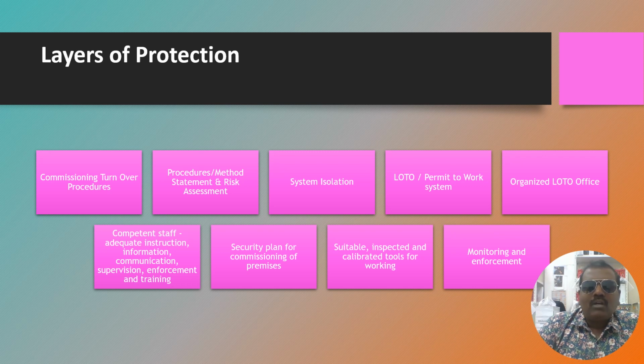How to remove this? A motor is to be energized now. How to remove the lock? There should be a criterion which is called the MCC package, mechanical clearance certificate. The construction person, the commissioning person and the QA/QC department should go and walk down to the site, visit the site condition and check all the factory test certificates and what pre-commissioning activities have been completed. Everything needs to be completed, and a checklist is to be assigned for each and every MCC package.